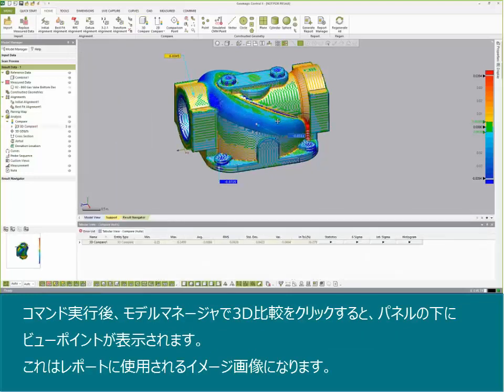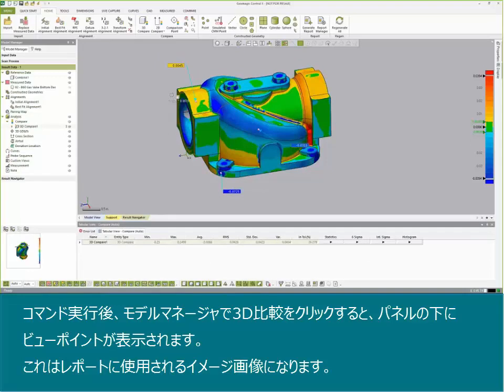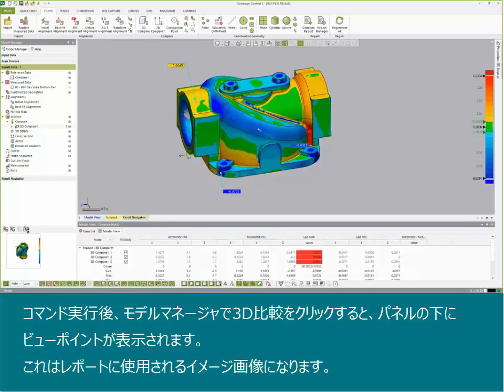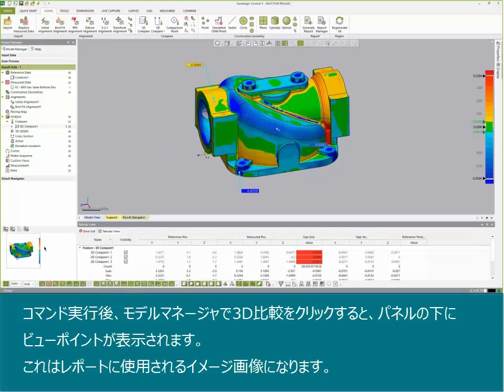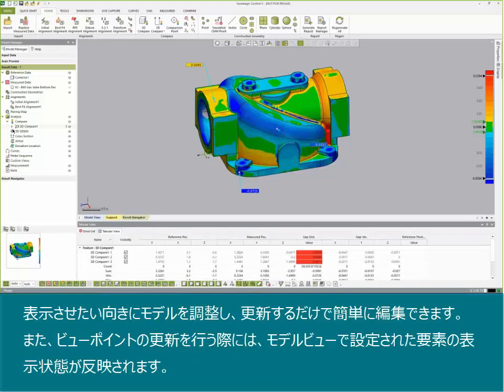Again, right away, all of our reviews, since we're not doing reference frame views on everything, we can automatically update stuff as we come along with our part to figure out what we're going to see in our report. These are basically all screenshot views. Every object has one, and it's really easy to come along and go through things. Again, feature tree based, so it's really easy to break out and adjust any items individually.